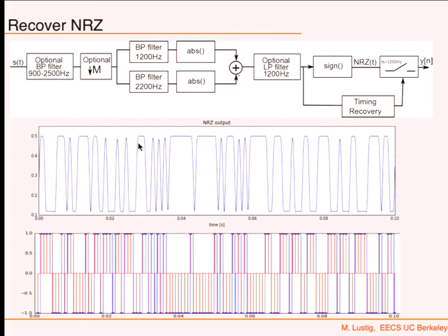You're going to encode, demodulate, and then compare the result of the output to the input. First, you're going to do that not within a function. You do it where you know exactly where it's supposed to start. And just make sure that these things work. You should actually look and debug, make sure that it samples at the right place. So you compensate for the right delays for the filters, and also get to the middle of a bit.